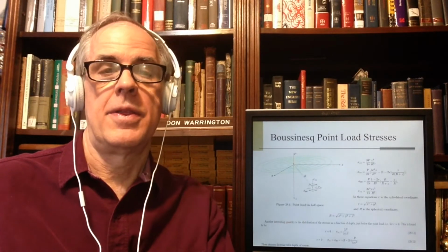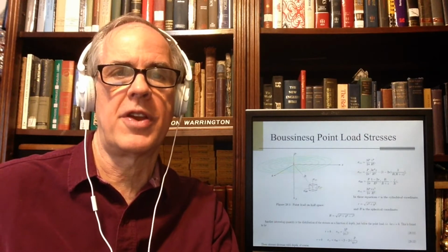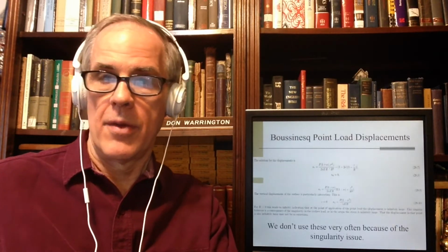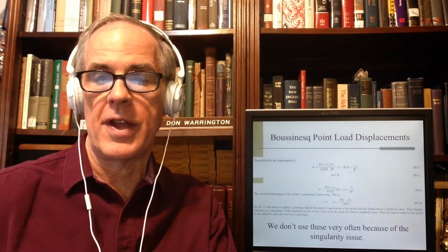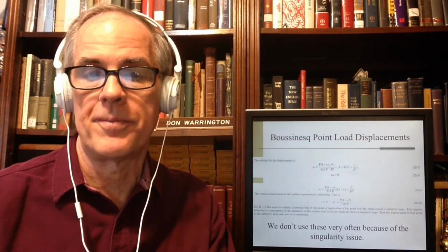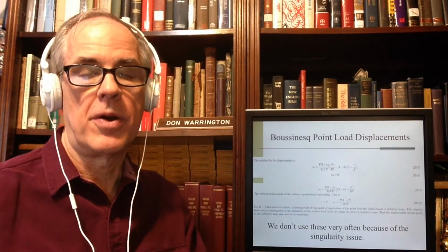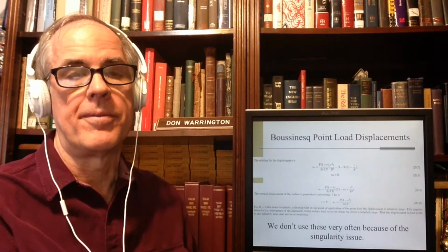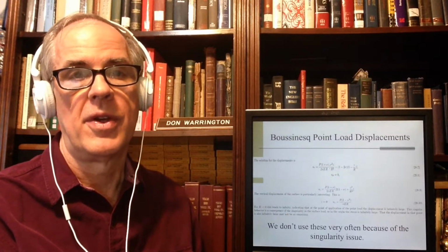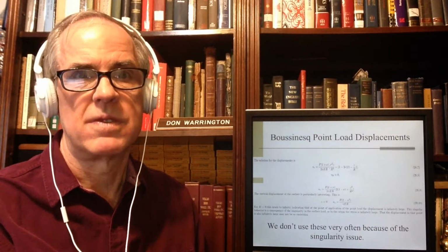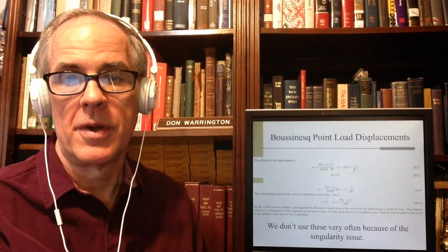But the Boussinesq point loads are a singularity. We have the same problem with the deflections. Deflections assume, for r, as r approaches 0, that radius approaches 0, I think it blows up for deflections too.